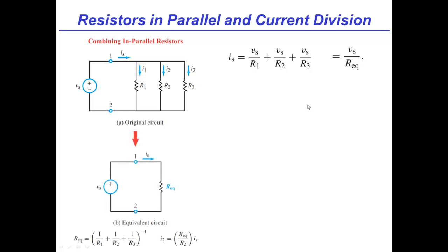All right, but where are you going with this? Oh, I see where you're going with it. You isolate out the Vs? Yep. And so then what you're saying is if I factor out Vs, I get Vs times something in parentheses here, and that's got to be 1 over R1 plus 1 over R2 plus 1 over R3, just by this expression.